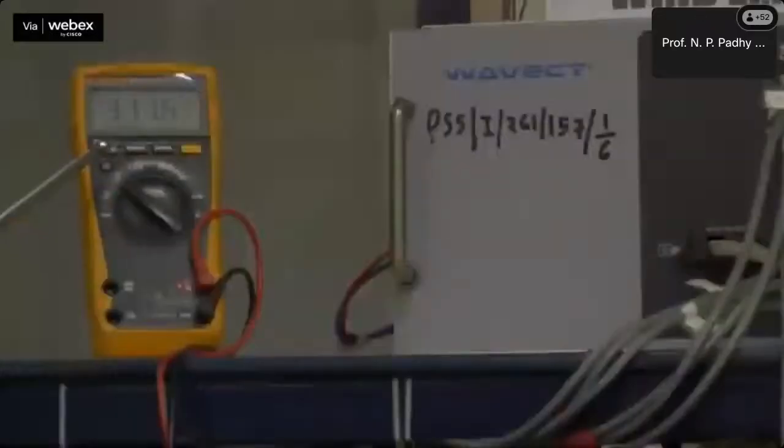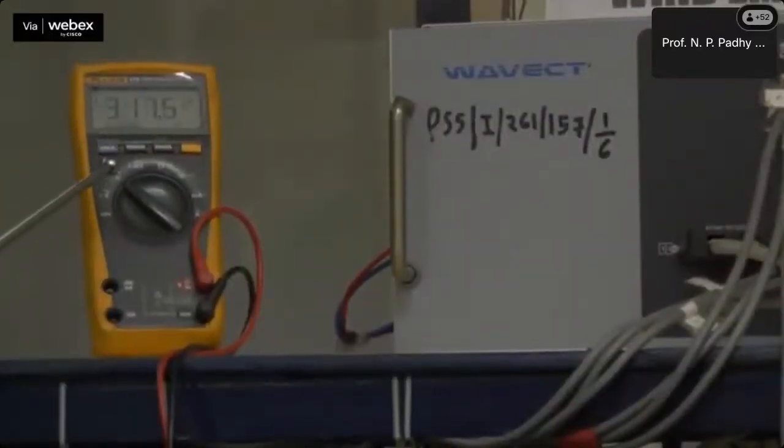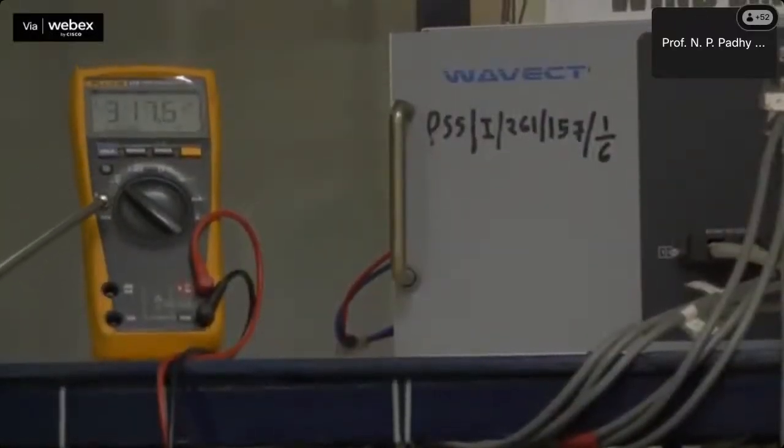The power amplifier voltage information is passed to the PLL of the FPGA controller to extract the grid phase angle. Then we enable the phase locked loop and check the reference theta with the phase A voltage.